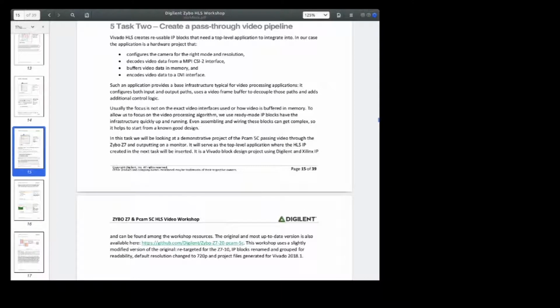Now, like I said, it is out of date, so you need to use the procedures I mentioned, which is opening in Vivado. Don't let it change anything. Keep it read-only. Then generate the hardware, and then import the actual application project, and let it copy it in here. So let's first go back.